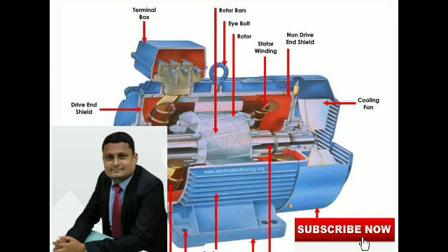Slot should not be too deep, otherwise it will increase the leakage reactance. So the guideline says that the ratio of slot depth to slot width should be 3 to 5.